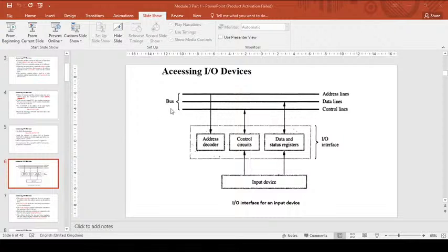Branch if equal to 0 to WAITD. If SOUT is equal to 0, that means the output device is not ready to display. So again go back to WAITD and check the same bit, the SOUT flag, again. Bit 1 of the status register is continuously monitored, and the program keeps branching to WAITD while it is 0.